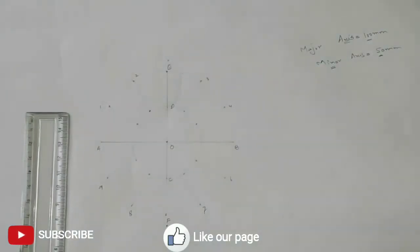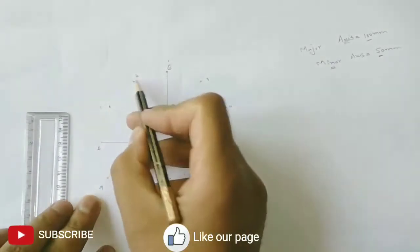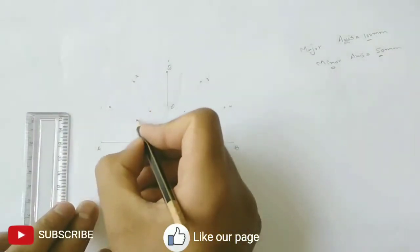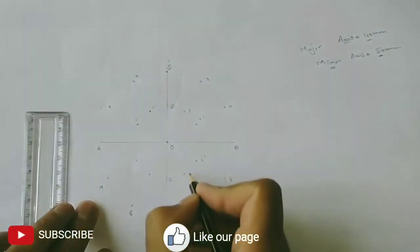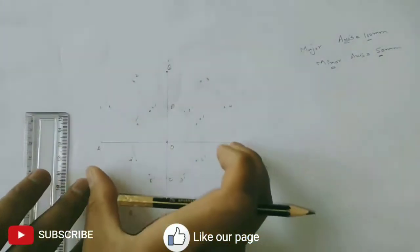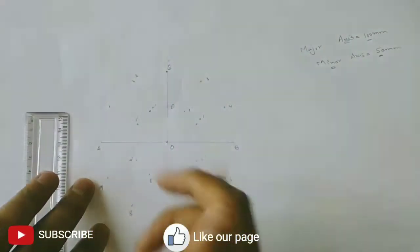Now, next, you need to draw the vertical lines from these points. That is 1, 2, 3, 4, 6, 7, 8, and 9. And horizontal lines from these points. Let me name this as 1 dash, 2 dash, 3 dash, 4 dash, 6 dash, 7 dash, 8 dash, and 9 dash. Alright. So you need to draw the vertical lines in the downward direction above this line AB, and in the upward direction below this line AB.